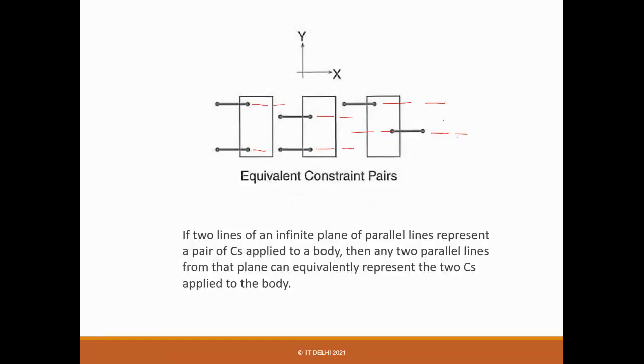What is important is this distance. This distance should not be 0. There should always be a gap width. Then only it can constrain the rotation. If it's 0, then they are collinear and it's an over constraint case.